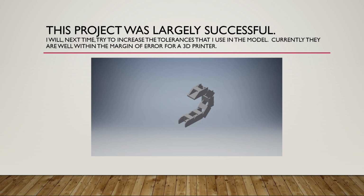The project has been largely successful. I did learn I need to increase my tolerances. Right now, the connecting points are only 0.02 millimeters different, which isn't practical for 3D printing. I mean, a small nozzle size is like 0.2 millimeters, so it's well within the margin of error, so printing this would be impractical. So I would definitely make that change. This simple video kind of shows the individual pieces of it as it comes apart.